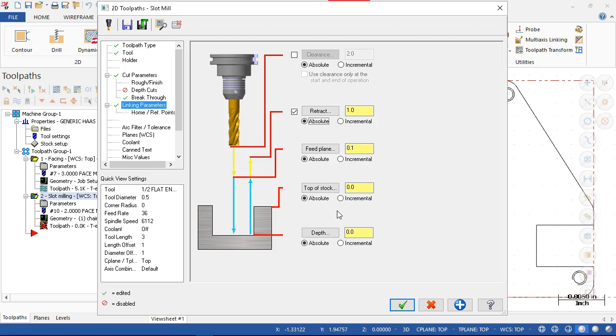It happens that it does the deceleration at 1 inch, and it's slowing up a little, just enough that it looks like 1 inch or it doesn't. And then as you are approaching the point, you hit the feed hold on your setup or your first go-arounds, and then that looks like 100 thousandths. Okay, go ahead and make the cut.